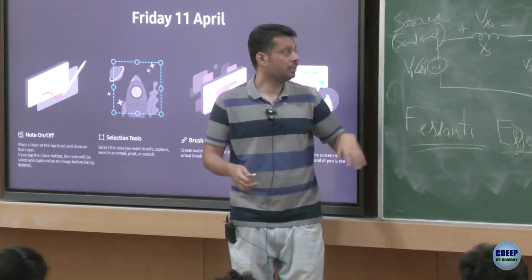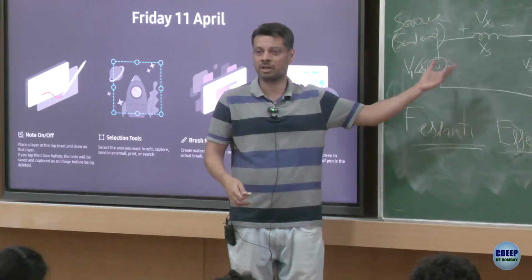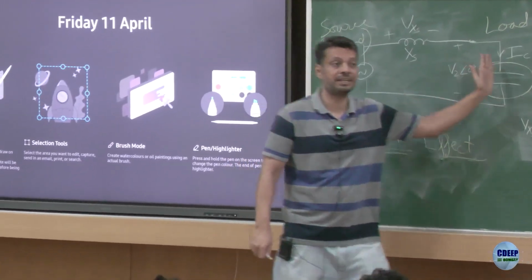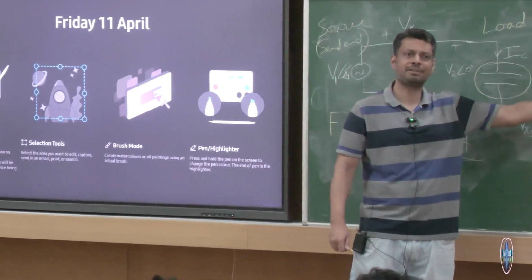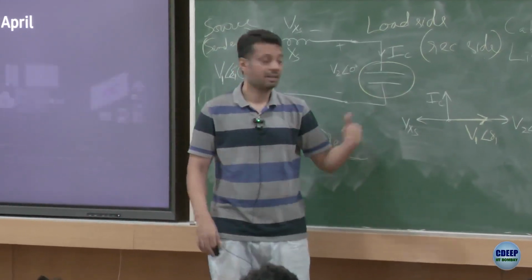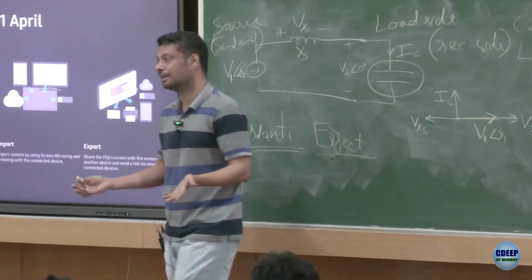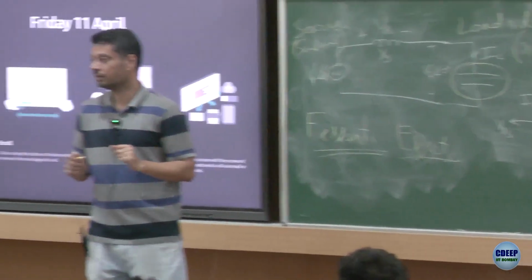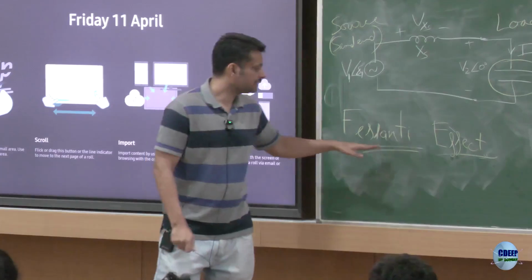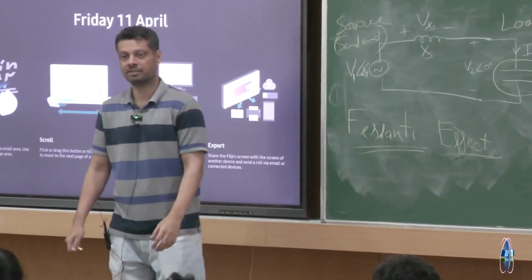Three, it's a short distance cable or line, but you had some capacitors connected here to compensate for the inductive loads, but those inductive loads are turned off. Maybe that industry shuts down in the night. Now you have these excess capacitors sitting there, so they would lead to the same phenomenon. So it could be these two or three reasons, right? And the name for this effect is the Ferranti effect.